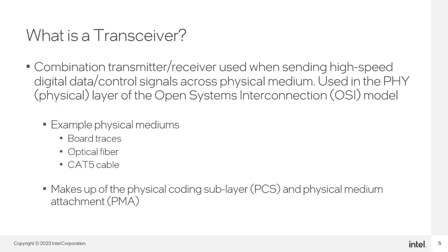Depending upon your physical medium and the high-speed protocol which you want to support, you may require specific features from your transceiver. Some application-specific standard products, or ASSPs, since they are designed to support select applications or protocols, will implement only certain features of the transceiver. Since FPGAs are designed to be generic and support a wider range of protocols, their transceivers are much more configurable.